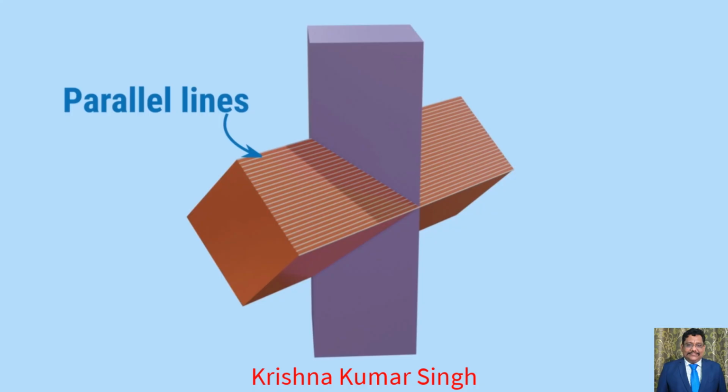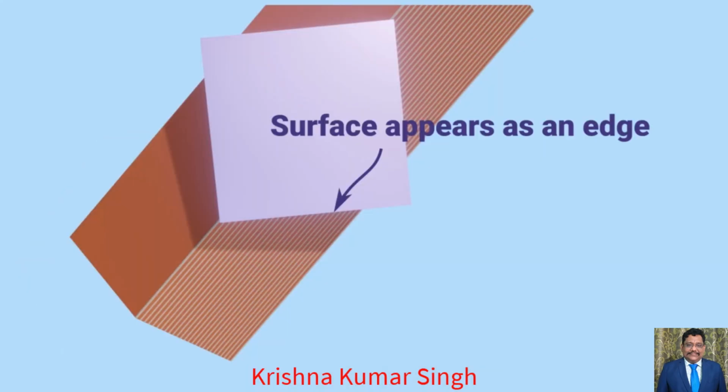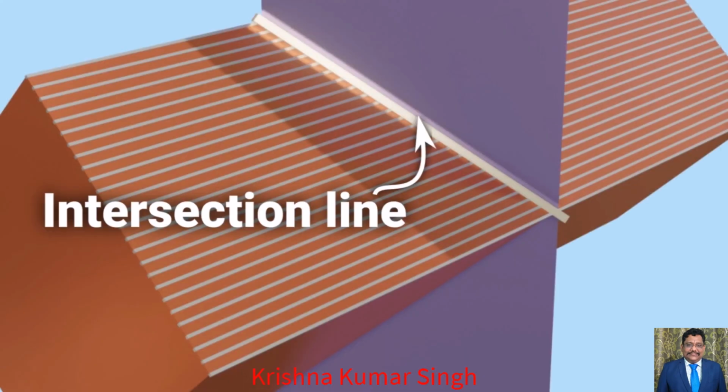Basically, in this method of intersection, firstly, lines are drawn from lateral surface of one solid and onto the line of intersection, then points of intersection of these lines with the surface of other solids are located which lie on the required line of intersection. They are more easily located from the view in which the lateral surface of the second solid appears edgewise, that is, as a line. The curve drawn through these points will be the line of intersection where both the solids share a common surface. This is how the intersection line of the solid is obtained from this method.